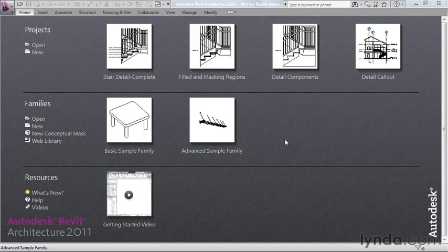In this video, we will establish the framework for our simple Revit model family. Using reference planes, we will establish the basic extents of our family and then assign some simple parameters to them to control their position. It is very important to carefully plan and build your framework before you attempt to add model geometry to your families.